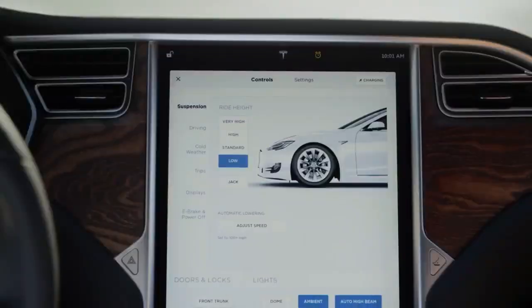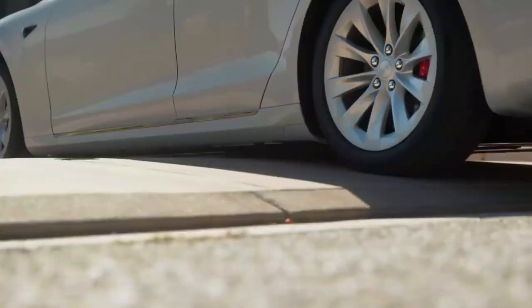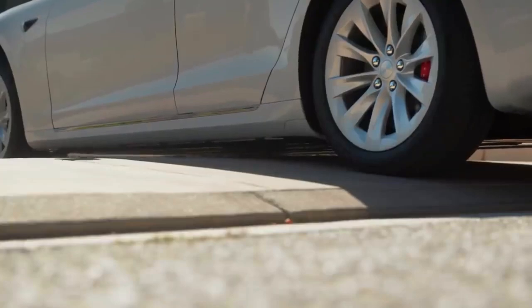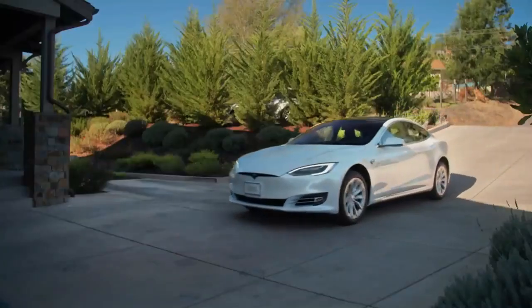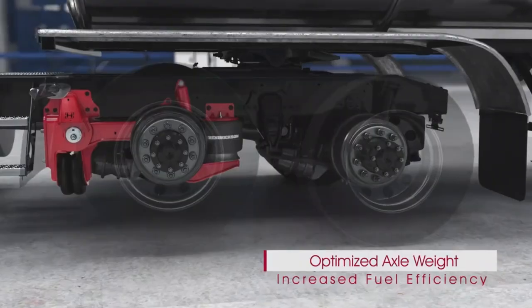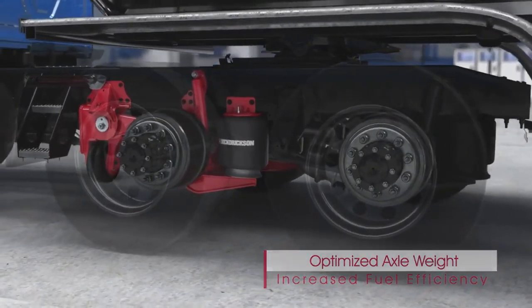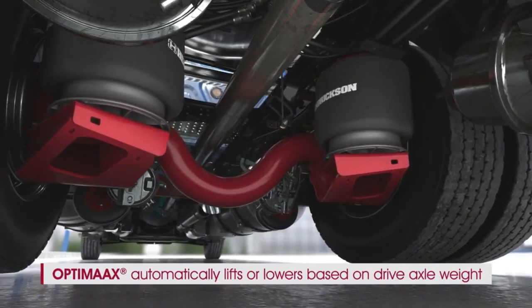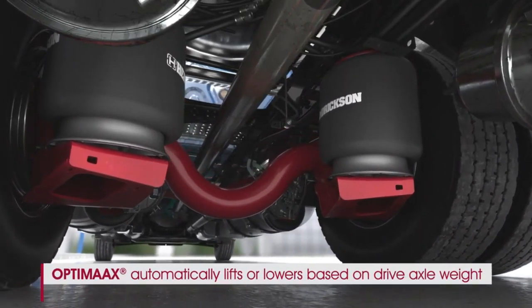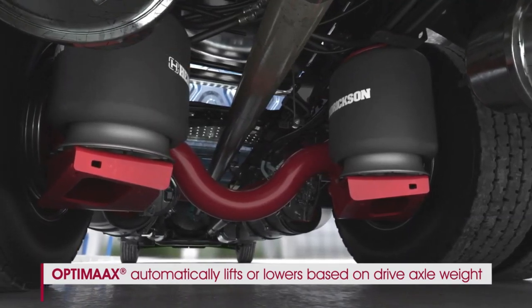Air suspension system definition. An air suspension system can be described as a suspension system that harnesses the qualities of air contained within a reinforced rubber column, often referred to as a bellows, to provide cushioning for the vehicle. These bellows are engineered to endure high-pressure air and undergo inflation and deflation as air is introduced or released, respectively. Unlike conventional metal springs, these bellows are employed to absorb shocks in the suspension system.